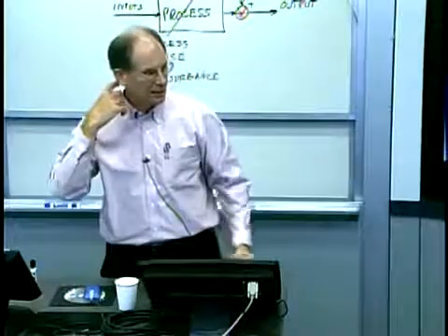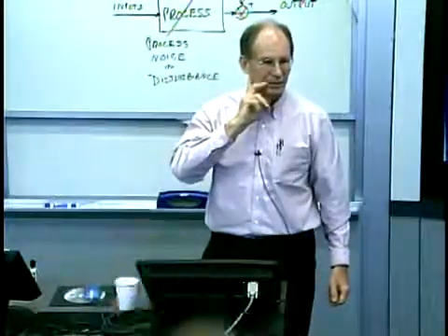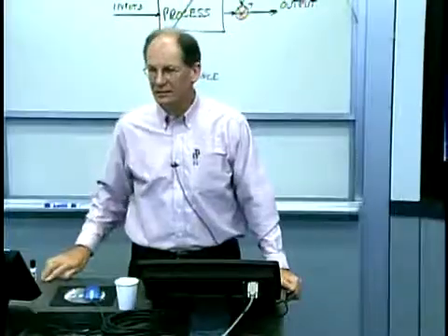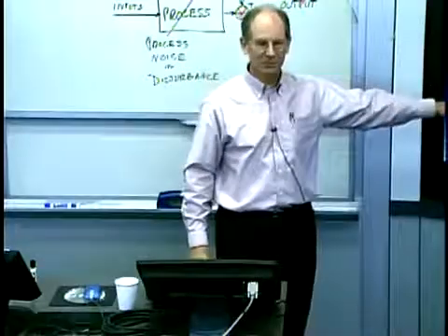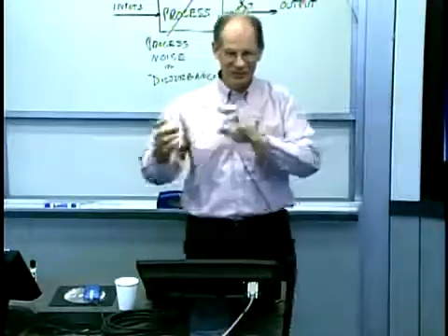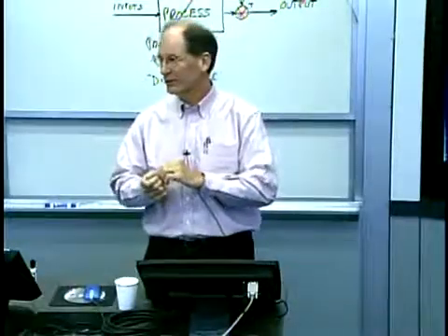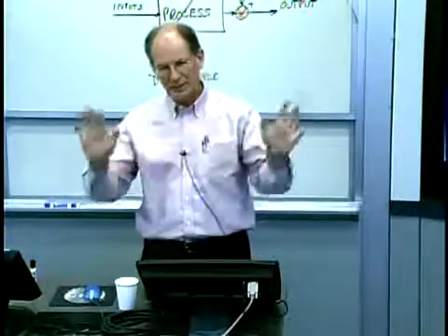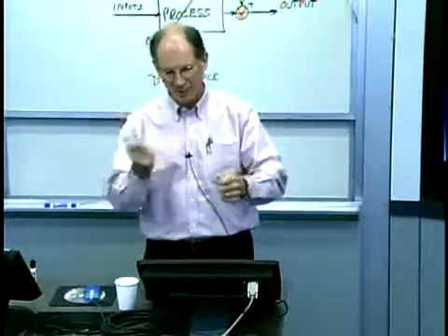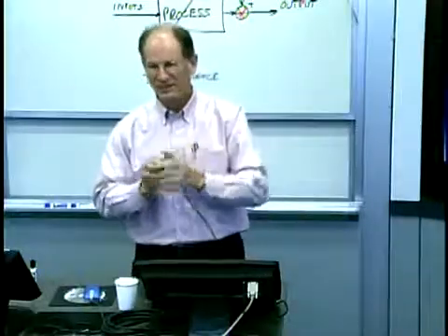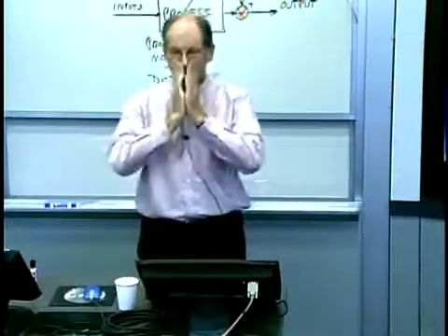Can you generalize that? Yeah, Kanika. This is not active control, but we could do some kind of cheating, like selective assembly. Oh, yeah, that's cheating. Selective assembly? Indeed, selective assembly is something that you do when this is the best you can do and it's not good enough. You just take individual parts and say, well, these fit, or you gauge. And that was also my aerospace example from a couple weeks ago, where you've got the people behind the curtains with the padded table and the padded hammers, and they're pounding things, and that sort of custom assembly. So you can do those sorts of things.